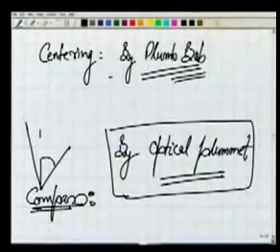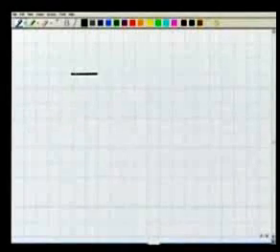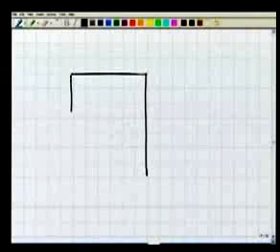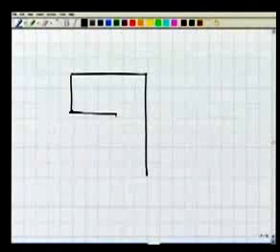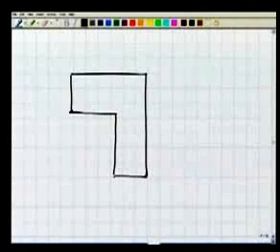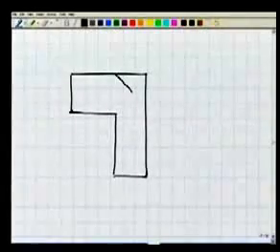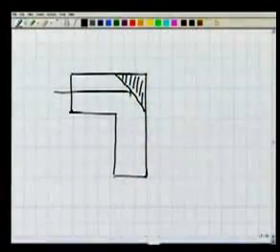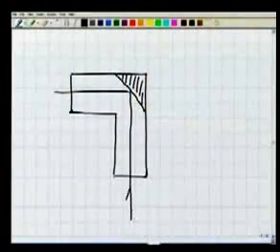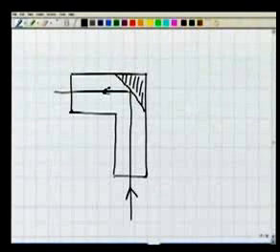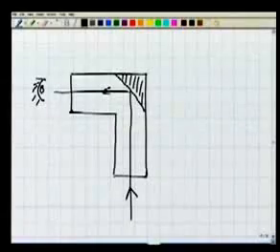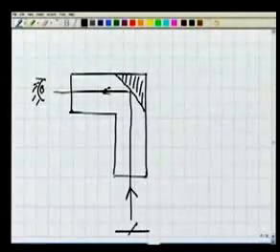What is this optical plummet? If I draw the line diagram of that, it's a very, very simple instrument. It may look like this. Now here we have a prism, and this prism's role is whatever the rays are coming from here, like this, it will transfer them, and here is our eye. Now this is the point in the ground.